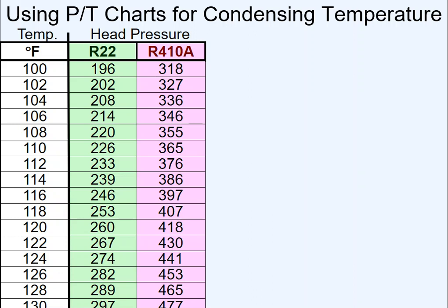You need to know, before you ever put a set of gauges or a meter or anything like that on a system and take a reading, you should have a really good idea of what it should read. And so all that you're doing is verifying that it's doing what you think it should do. If I were to come up to you before you ever put anything on, and I say, before you do that, because I will do this a lot, what's it going to read when you put it on there?